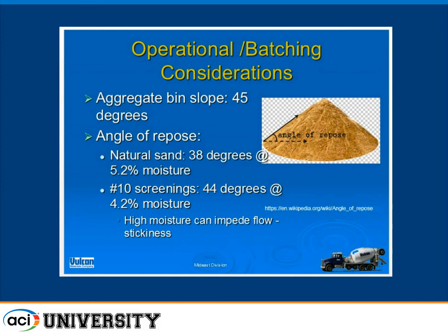In contrast, this particular number 10 screening source has a 44 degree angle of repose at 4.2% moisture. One of the things you need to know is that if the moisture goes higher, the angle of repose is going to increase. That's true in natural sand as well as in number 10 screening. But there's an added challenge in the number 10 screening.